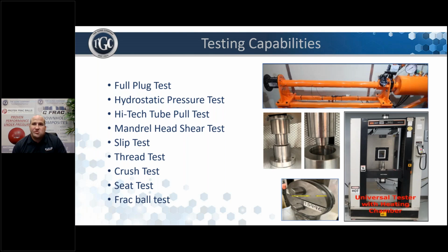We have a hydrostatic pressure chamber, which allows us to put a full plug or tube into casing and pressure up on it until failure. We also have a heater chamber with a pressure pump that allows us to do full plug testing. This starts at a setting simulation and can take it to failure as well.